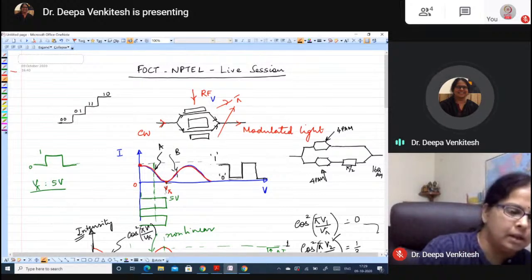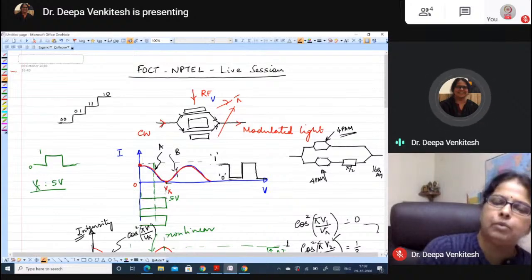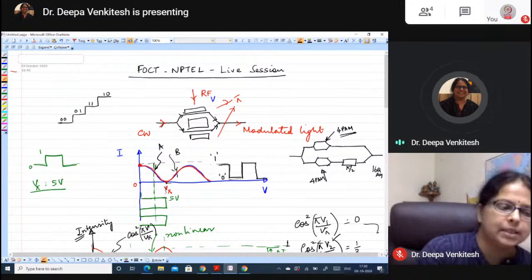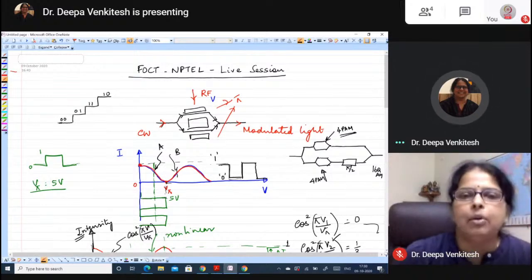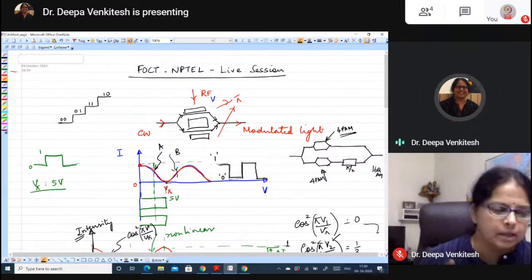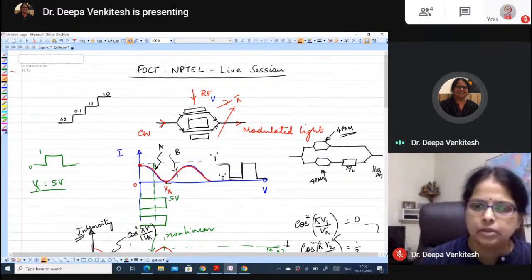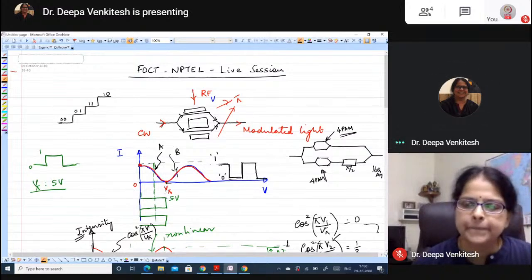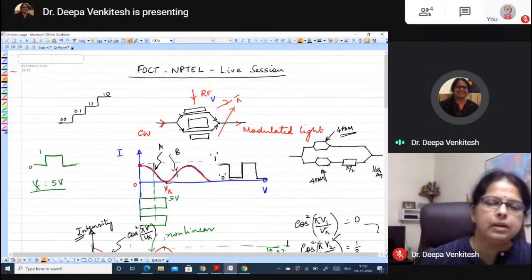Right? So even here, in each of these cases, you will pre-equalize your 4 PAM voltage levels so as to undo this modulator nonlinearity that I was talking about. Okay, so I hope that is clear. Arjun, is that okay? There's no difference between 4 PAM and 16 QAM in that sense.